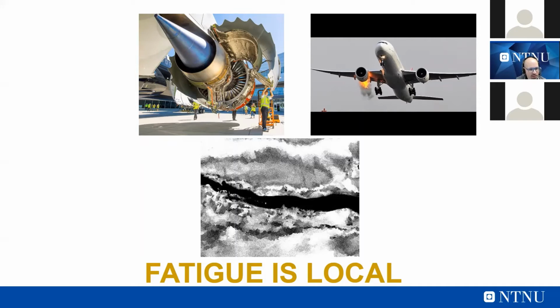an example of an engine of an aircraft. Or we can make other examples that are built for civil construction engineering. So big components, for example, that we use and that are subject to cyclic loading. Usually we have to design these kinds of components, and the fatigue initiation life or fatigue propagation life always starts from a localized place inside our component, where the crack, for example, is very small in scale with respect to the size of the entire component, that can be, for example, meters, while the crack can be 0.1, 0.01 millimeter. So we have a span of scales from the crack length to the real component.